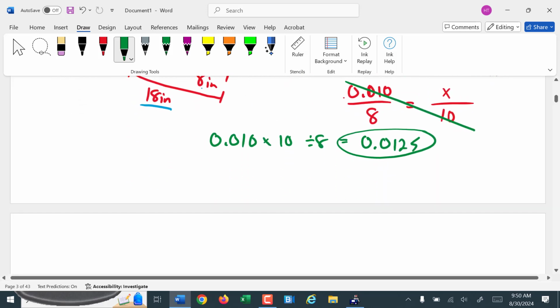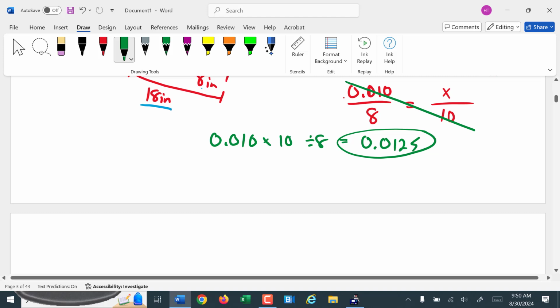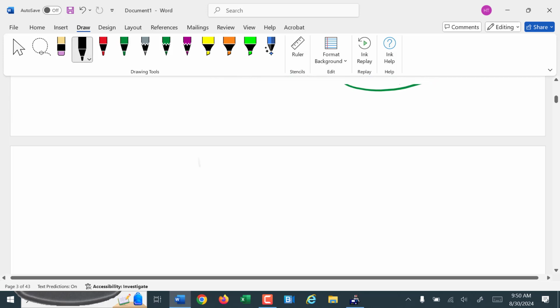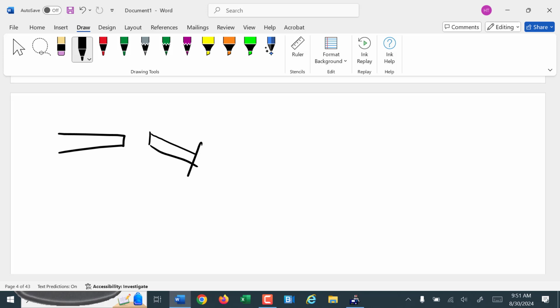So you'd end up shimming at either 12 thousandths or 13 thousandths. I don't think any of you have a half a thousandth shim anywhere, do you? I know I do in some of the mechatronics stuff. In the mechatronics lab, I think we have 2,000 shims, and those get pretty, it's like running aluminum foil underneath the thing.